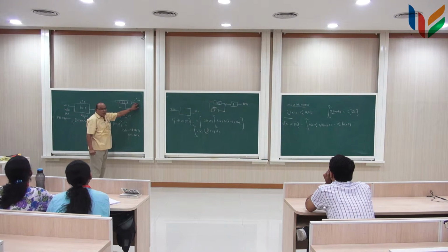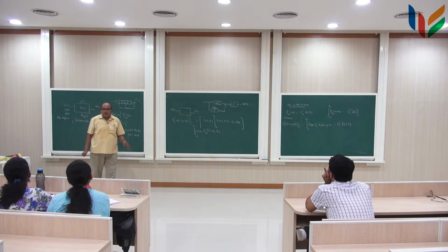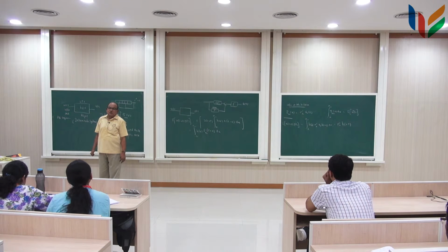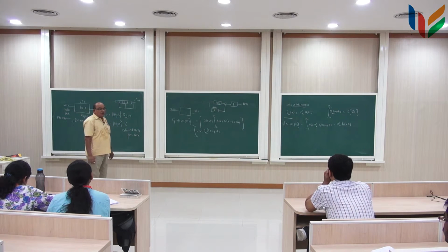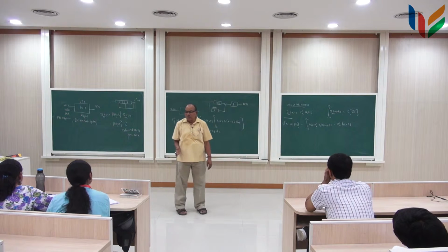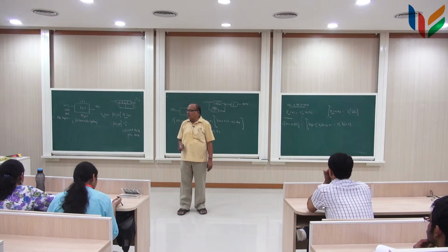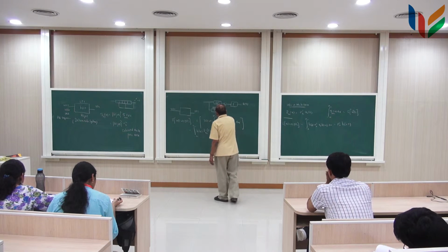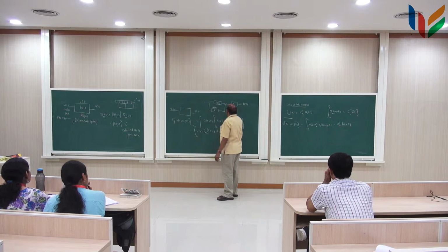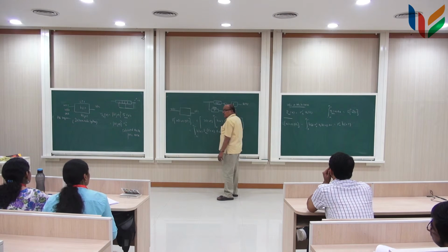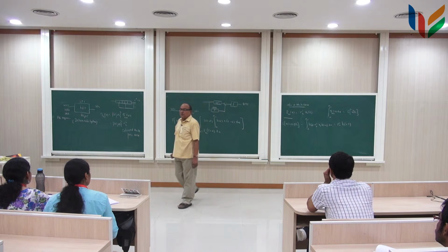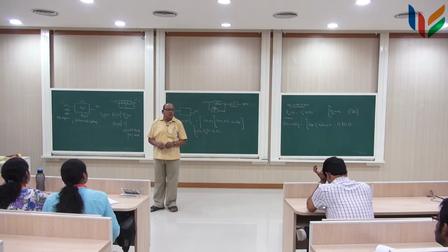And the function you get here has a correlation function which is approximately the same as the correlation function that we are looking for. So people use a deterministic function which approximates a random white noise by using the PN sequences, and test this system by using that signal here and delaying it by some fixed value of tau, and evaluate the integral here and get the value of h at that tau. Change this, get a different value, change this. So you can scan the whole h of t. So it's a very beautiful way of doing it.